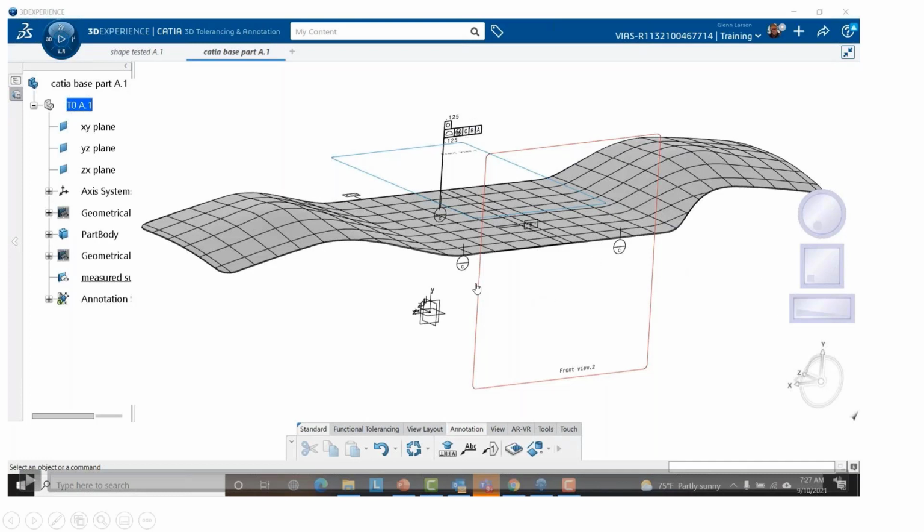And I have some target datums of where they're going to set that on some stands on their scanning machine. And so we have a datum. And one of the things I'm going to say is really important is how you set your datum up. Now you can move things around in here and scale them very easily, but it's always best if you can bring the part in the same datum.